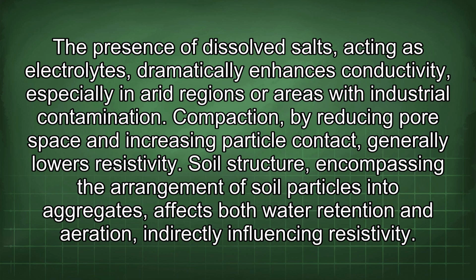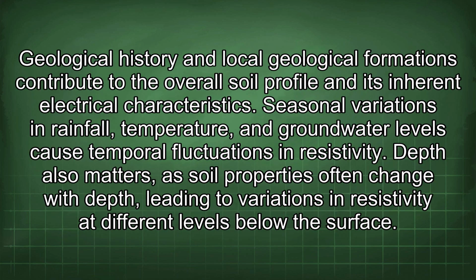Soil structure, encompassing the arrangement of soil particles into aggregates, affects both water retention and aeration, indirectly influencing resistivity. Geological history and local geological formations contribute to the overall soil profile and its inherent electrical characteristics. Seasonal variations in rainfall, temperature, and groundwater levels cause temporal fluctuations in resistivity.